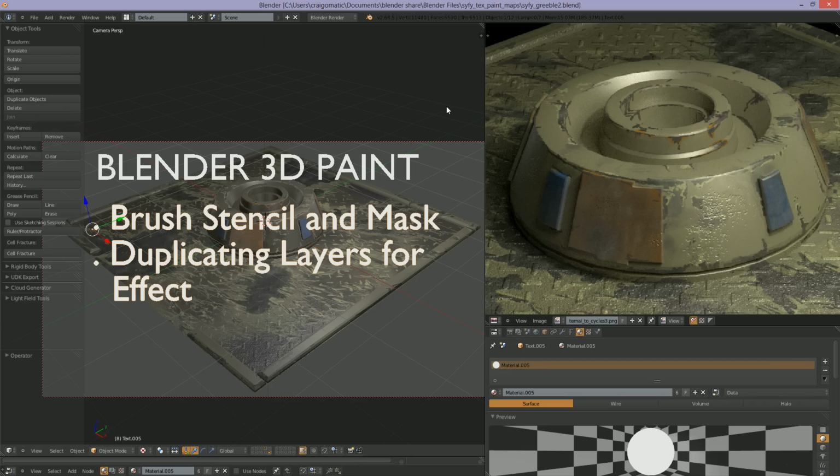Hello again. We're going to pick up in Blender 3D Paint again on another topic, just extending into the same workflow that I was working on in the previous three chapters. This one is on using the brush stencil and mask when you're texture painting. In that, what I want to do is show you how to go about setting up something to use as a stencil, and also, in the case I'm going to do, setting up a procedural texture to act as a mask on the stencil brush to paint something in 3D here.